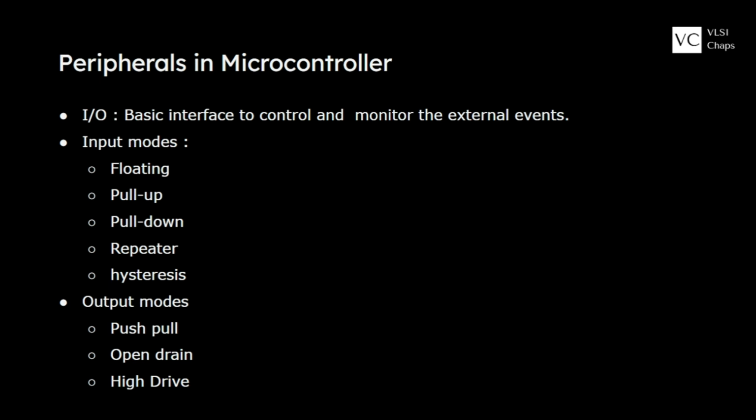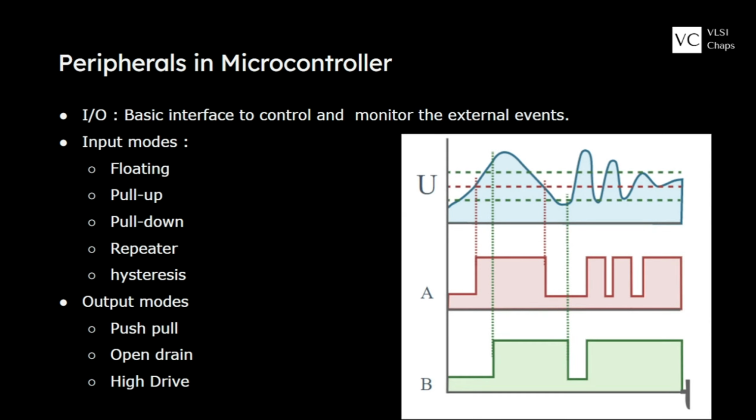If we talk about hysteresis, then this is a very special kind of behavior of a particular pin. We have experienced that whenever I push or pull the button, for a very micro period of time, there is no defined state of that button, either high or low. We will have various waves in between, which is called a spurious response of a particular event or button, or you can say the shaky power.